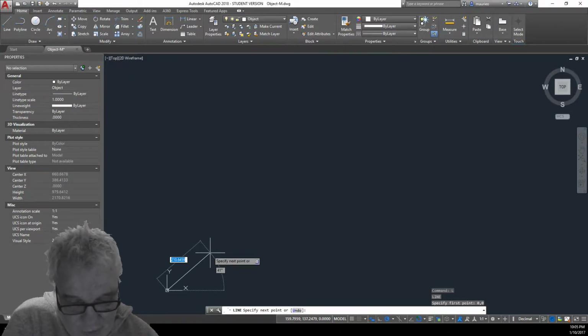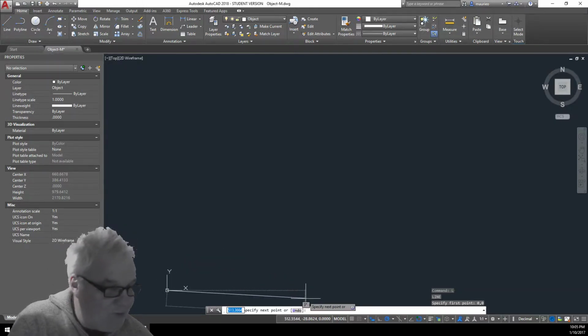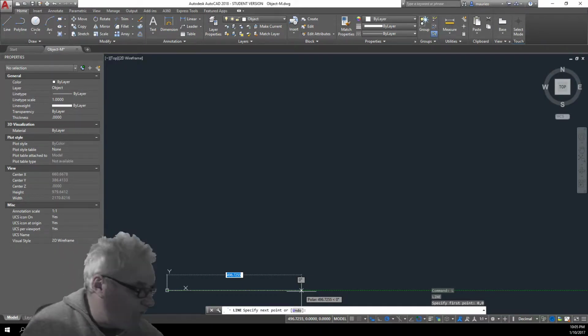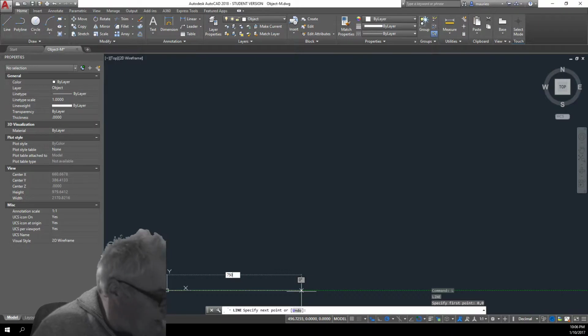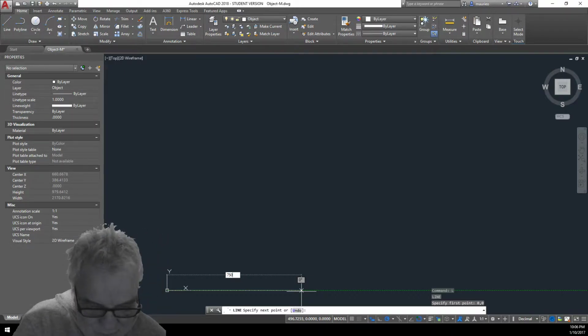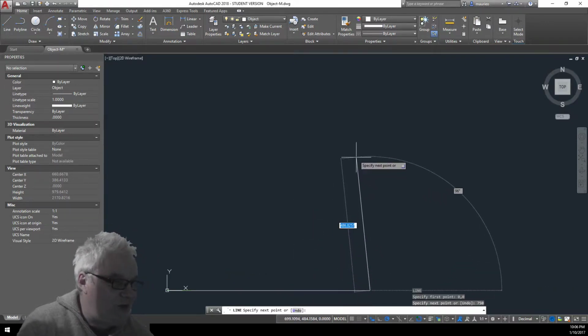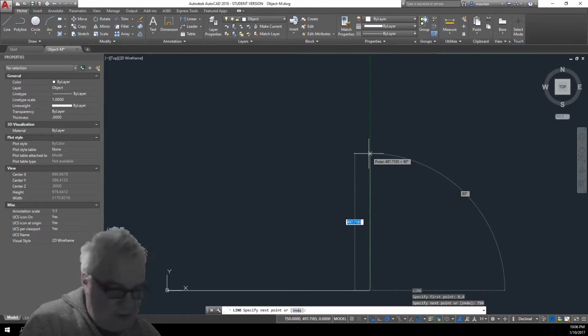So now step 3, move the crosshair straight to the right from the start point, like that, and you might want to pan down to there. When the tracking line displays with polar distance 0 as shown in the picture, type 750, which automatically overwrites the value in the edit box, and then push enter. Okay, so that's given us a 750 line there.